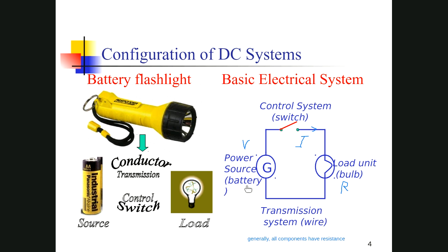When the battery is under load again and again, the chemical force to separate the charge becomes weaker and weaker, so it cannot output bigger current in a short moment. As a result, its internal resistance becomes bigger.